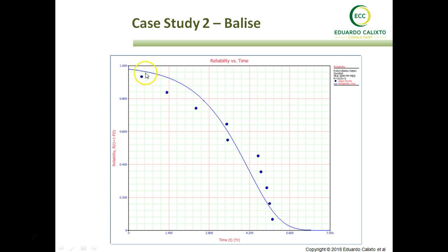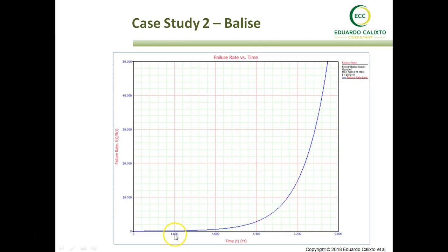We have some failures in the beginning, before 1 year, and we can also plot the failure rate. So we need to find out why this electronics has this Gumbel PDF based on the FRACAS cases, and if it's really effective, some actions are to be carried out to avoid such events happening.